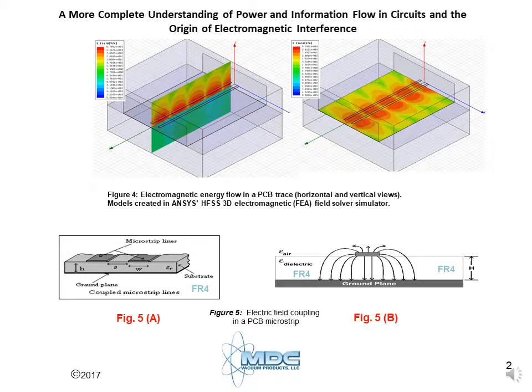What is shown is the electric field disturbance traveling along the trace. A magnetic field is also present, but its magnitude is so small compared to the electric field that it has been ignored in this simulation. The electric field is traveling at the speed of light in that medium. The speed of our simulation has been reduced so that we can actually see the field moving.